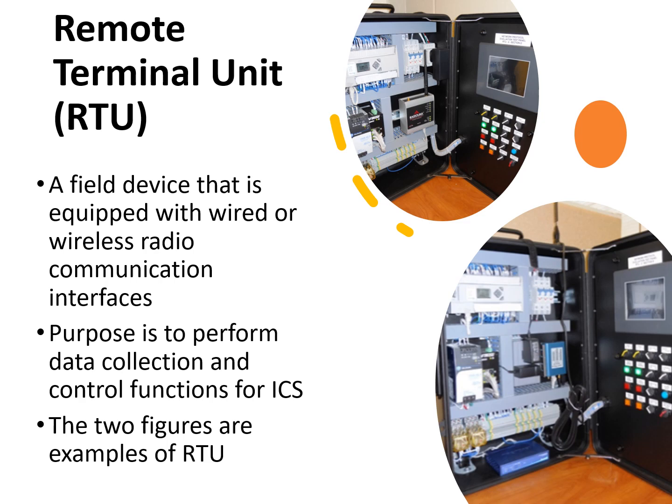Radio communication protocols may include 802.11 Wi-Fi, 802.16 broadband, 900 megahertz radio, and others. The RTU on the top right corner is controlled by a 900 megahertz radio transceiver. The RTU on the bottom right corner is controlled via cellular communication.